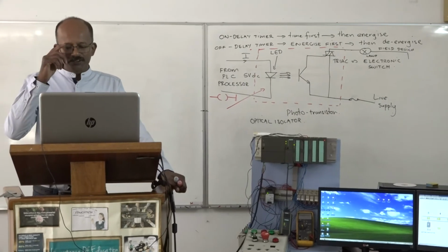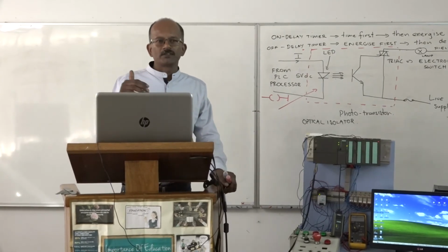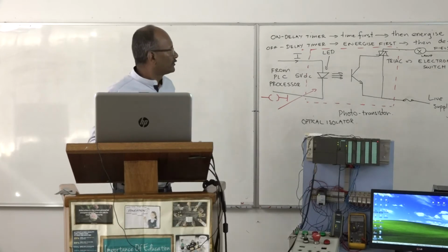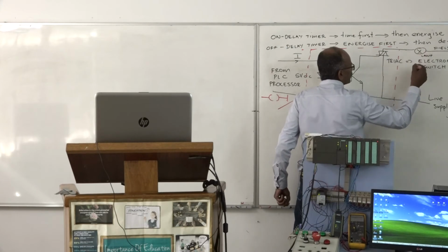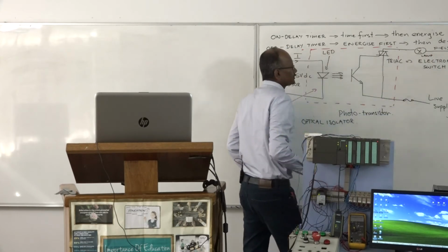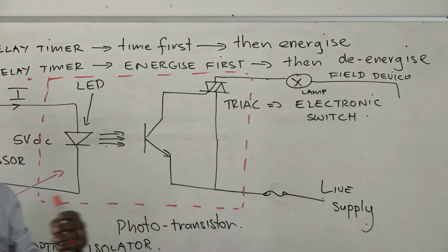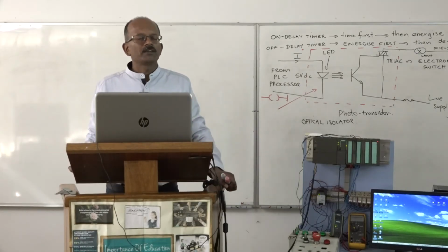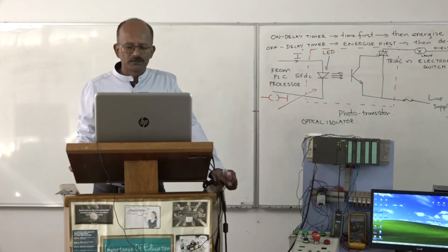So once again, please remember that your output coil in a ladder diagram does not represent a contactor or a relay. Instead of a lamp here, I could have a 24 volt contactor to switch on a motor. I could have a 24 volt relay here, like you would see later on, to switch on lights. I hope that brings some clarity on the symbol of the output coil.